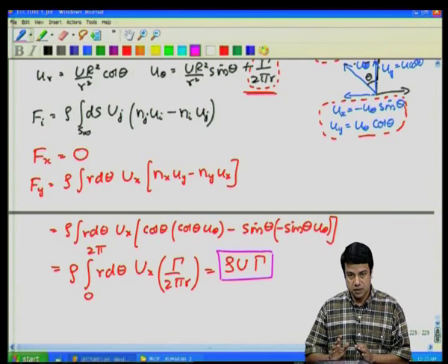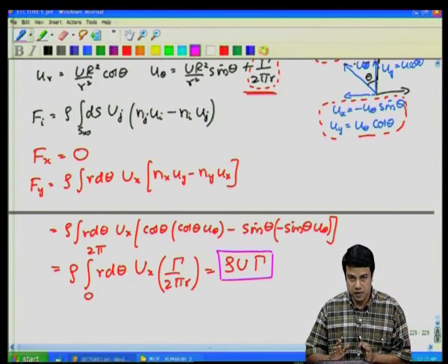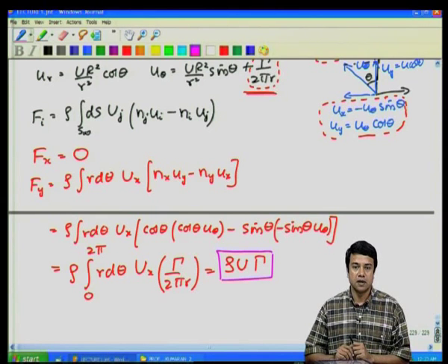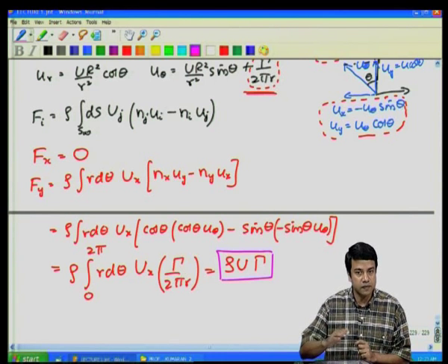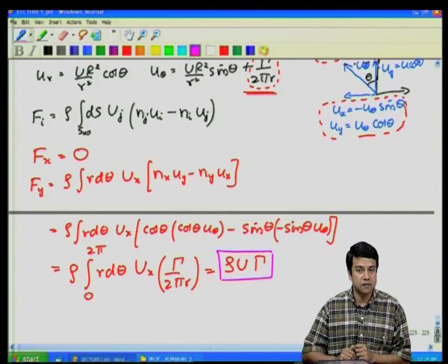This result, as I showed you, holds only for two-dimensional flows. That is the reason that aircraft wings are long and slender objects, because you require that the flow should be approximately two-dimensional at every point along the wing. Otherwise, you cannot generate a lift force.